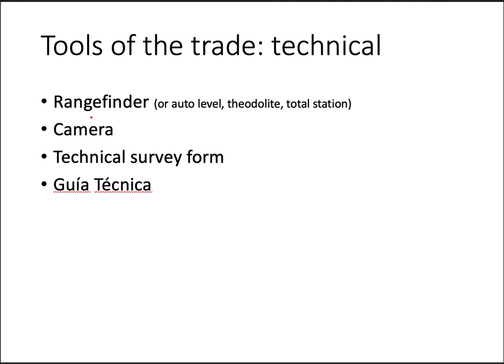When you go to this site, you're going to have to pick a site that very quickly looks like this might be feasible. Take these measurements, test it against the big 4, see if it works. If it doesn't, continue going upstream. Typically, I recommend going upstream around 200 meters and going downstream around 200 meters to try and find a spot somewhere along this profile where you can meet all of the requirements of the big 4.